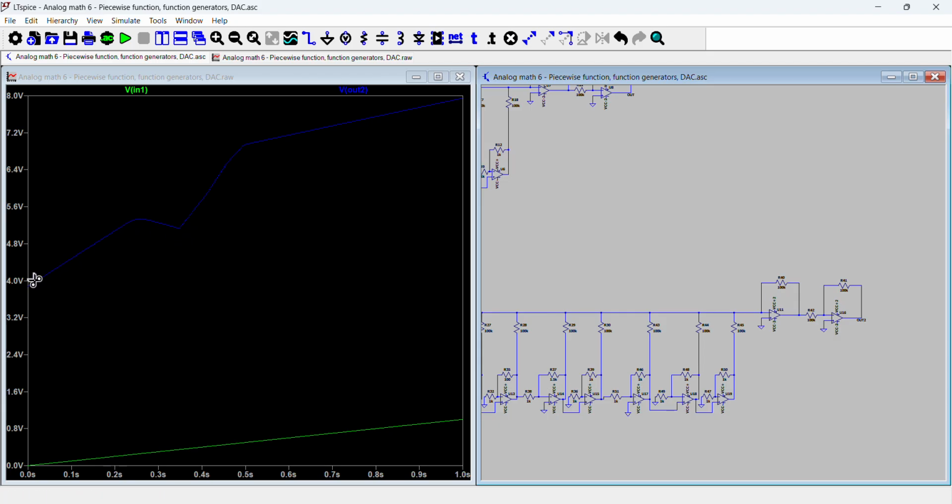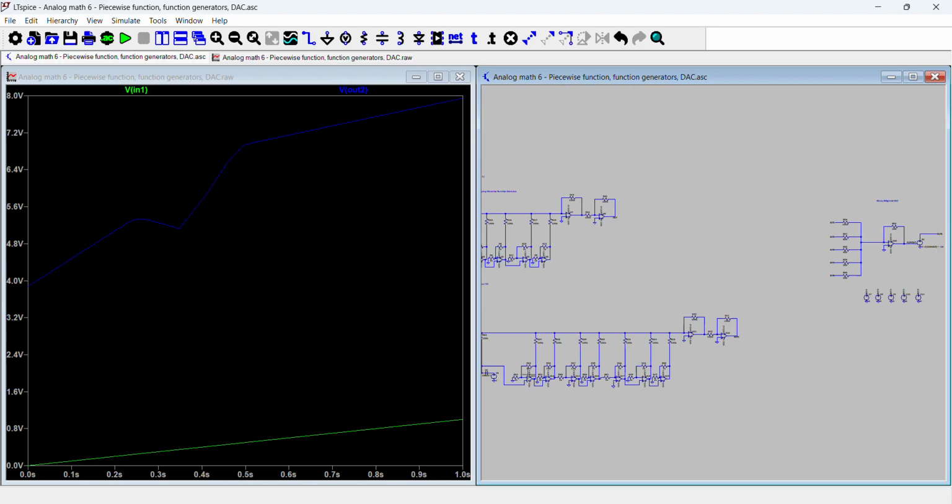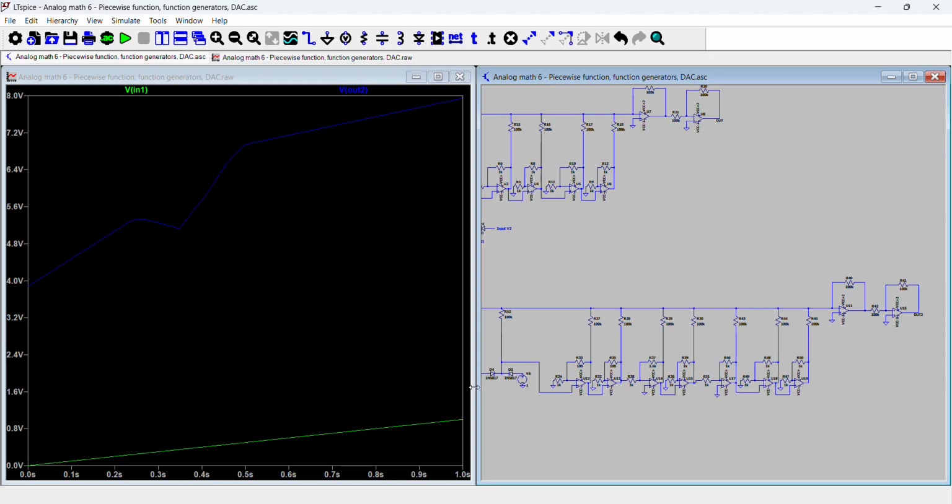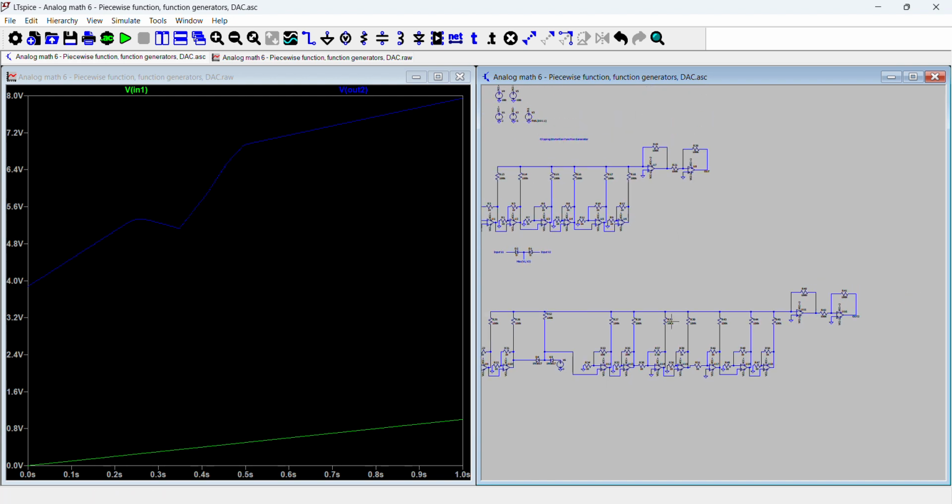And then you can see that the slope actually increased again. This is caused by this stage, the max of the two voltages stage. Using these building blocks, you can cascade things in a way such that they add up, the voltages of all the stages sum up together to be any function. And so you can basically approximate any piecewise function using this concept.